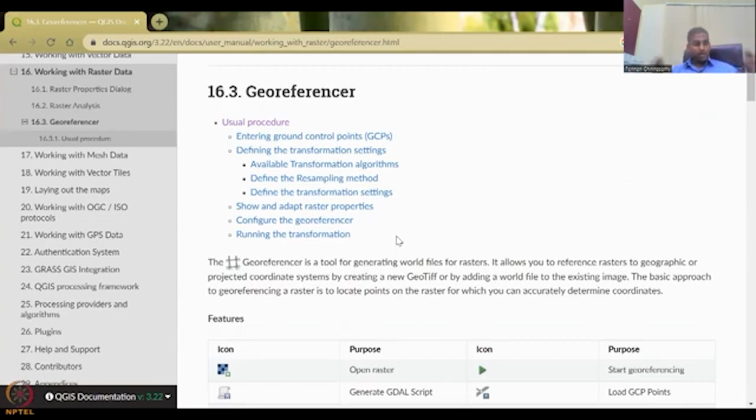So you have an image frame. In the image frame, I'll just show a paper example. Let's say the whole image is in the center, but you have a full A4 size map. What you will do is anchor 4-5 points along the paper, and throughout the paper it will interpolate. That is how the paper map becomes digitized in your model.